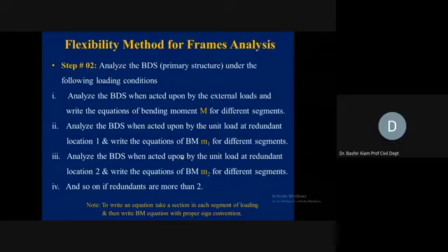This is the same as what you did in the 4th semester for finding displacements at various points in the case of frames. You have already discussed the virtual work method: at the point where you are investigating the deflection, we apply a virtual load of unit intensity. This is the same thing.